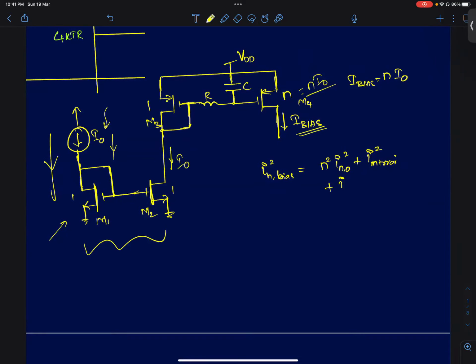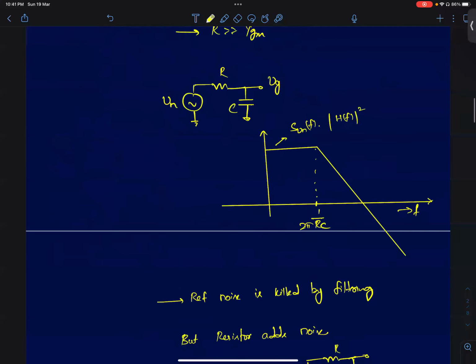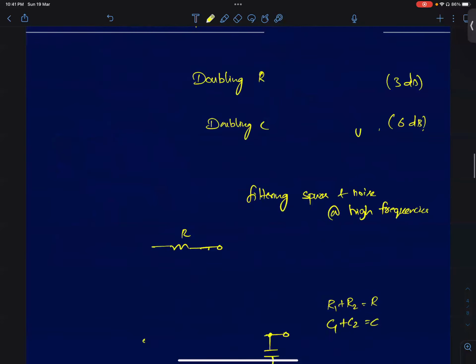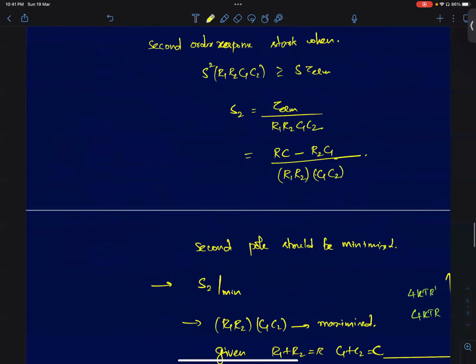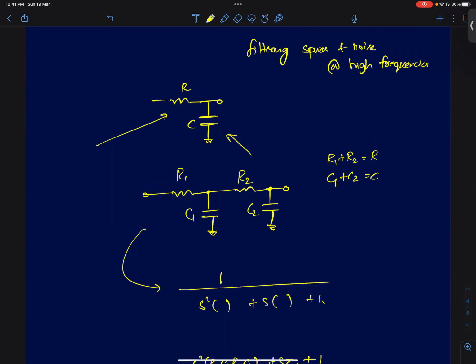One classic way of doing that is just put a filter, RC filter. Okay, we'll go deeper into why we should choose this capacitor with respect to the ground and supply and all that at a later stage. All I'm trying to tell you is that you have some noise source and you want to filter it out. And to filter it out, you're using an RC circuit, which is shown. Okay, so you're using an RC circuit to filter out the noise. You can also filter spurs. In my application, I was trying to filter out spurs. So I'll come to the problem.